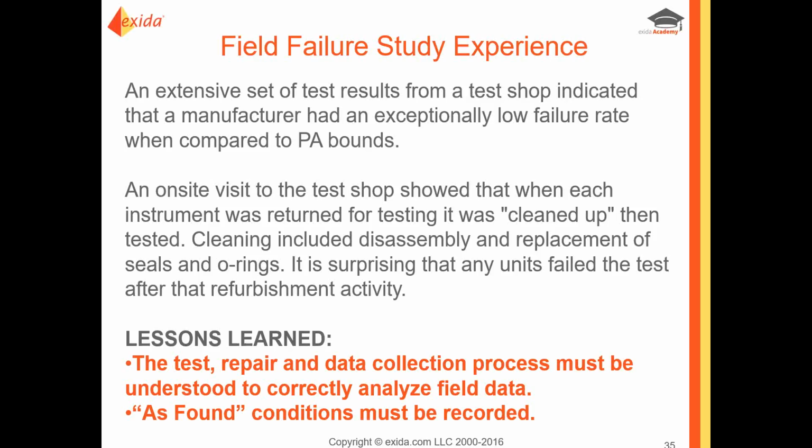What we discovered was that every time a pressure relief valve was returned for testing, it was cleaned up before testing. Cleanup included disassembly and replacement of all the seals and O-rings. And I was thinking to myself, my goodness, they have refurbished the entire unit. I'm not even sure that any failures would occur after that refurbishment activity. Think about it.